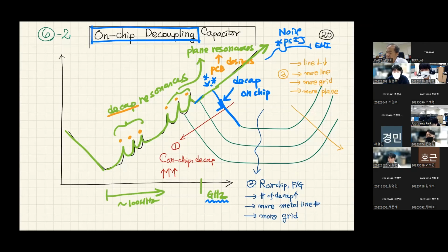However, even though you have a certain amount of on-chip decoupling capacitors, they have to be connected to your digital circuit. That means you have certain interconnection inside the chip, which has certain resistance. Because of the high frequency nature of the switching current, and inside the chip the metal thickness and width are very small, resistance is quite considerable inside the chip.